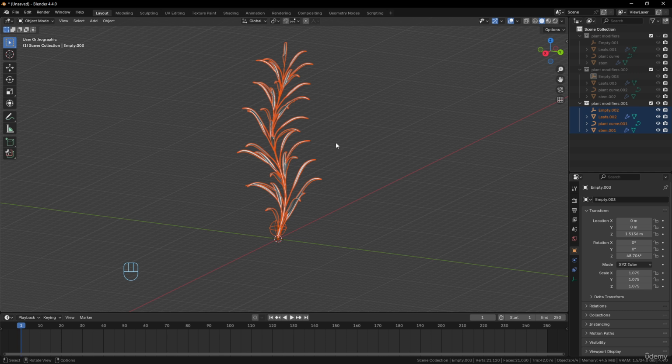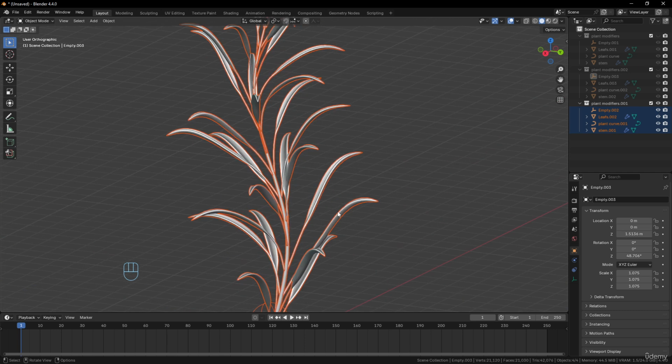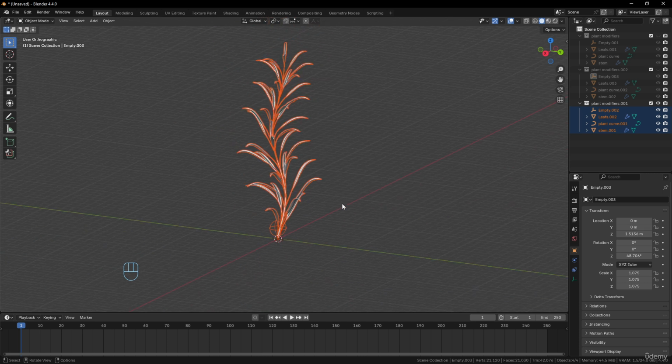So in that case, make something more low poly with fewer polygons, or don't use the subdivision surface modifier, to create as few vertices as possible in your scene. It is very important to keep the scene as light as possible. So that's it for modeling a plant, and in the next video we will see how to model a bottle with modifiers.